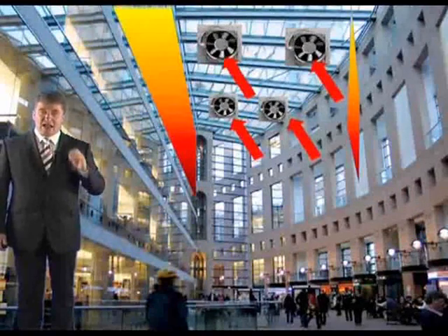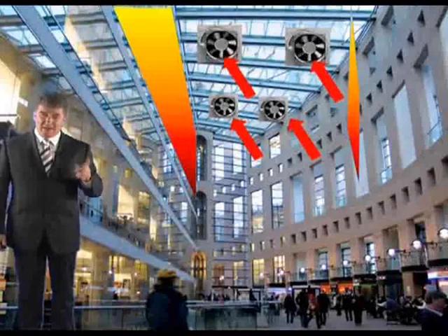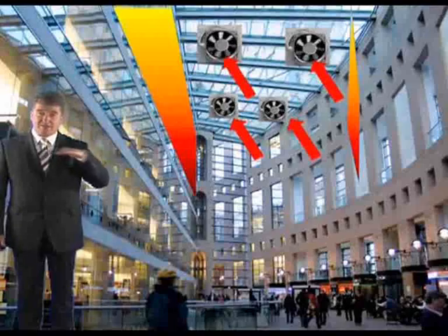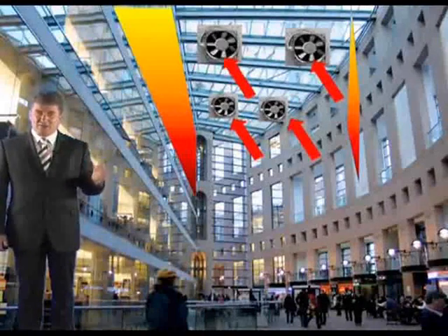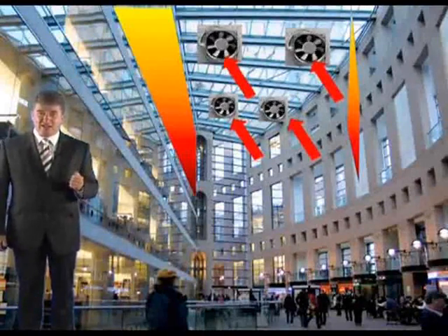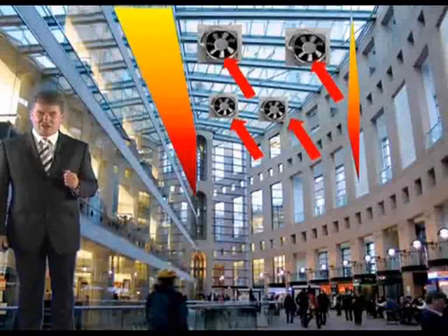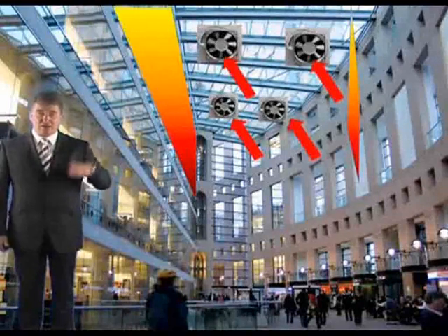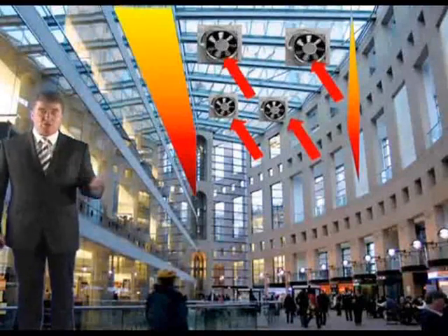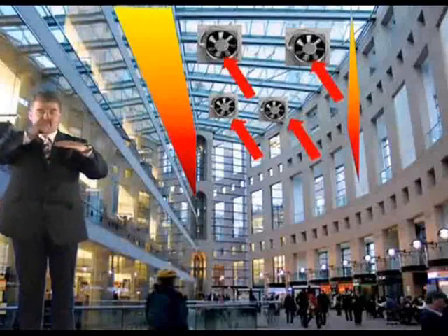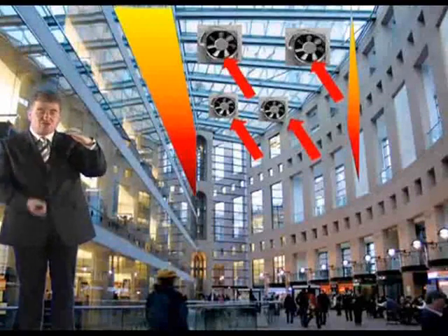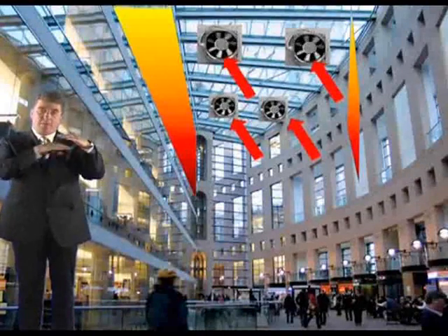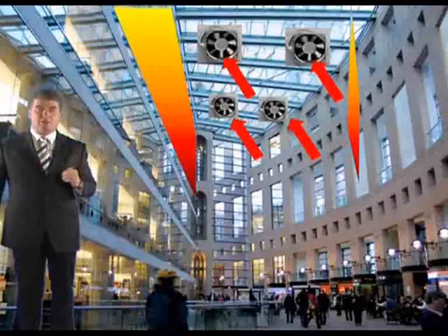Secondly, there must be a form of extraction of the smoke within the reservoir to prevent the smoke layer building down below what you classify as the design depth. This can be natural, which is buoyancy-driven ventilation, or it might be mechanical extraction, depending on the circumstances. And the rate of exhaust must equal the rate at which the smoke enters. That's what you've got to do when you work your calculations out. The extraction rate must equal the mass flow rate of smoke when a fully developed fire's gone. And if you can match that up, you've got your clear layer height, you've got your equilibrium height.